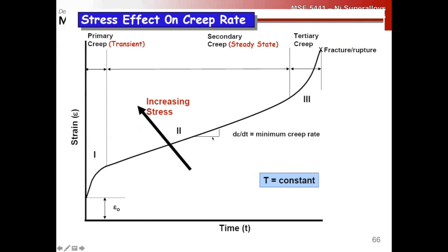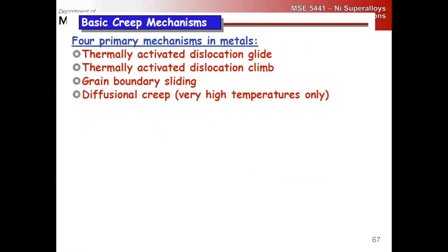And when we think about secondary creep, this essentially means that we're in a regime where the microstructure is fairly constant, right? Think about a stress strain response, and how would it stay at a constant deformation rate if the microstructure itself was not in approximately a steady state, right?